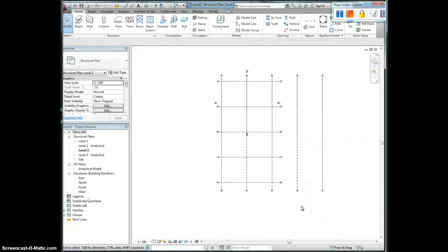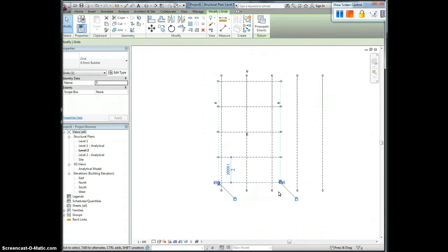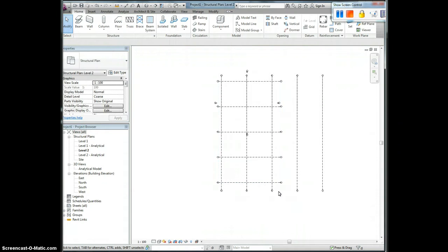Now, the horizontal grid line is not long enough. How? You edit. You press the escape key twice, then we go into editing mode. This portion you need to be careful. If you do not press the escape key, you are still in the offsetting, picking up the line, drawing offset lines. Then that can be dangerous.